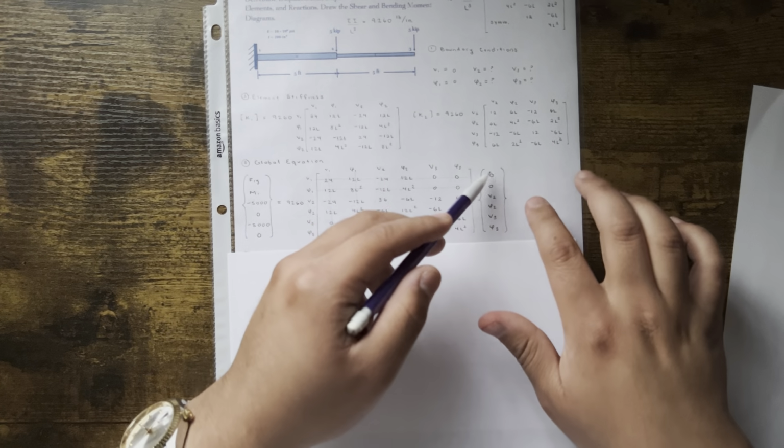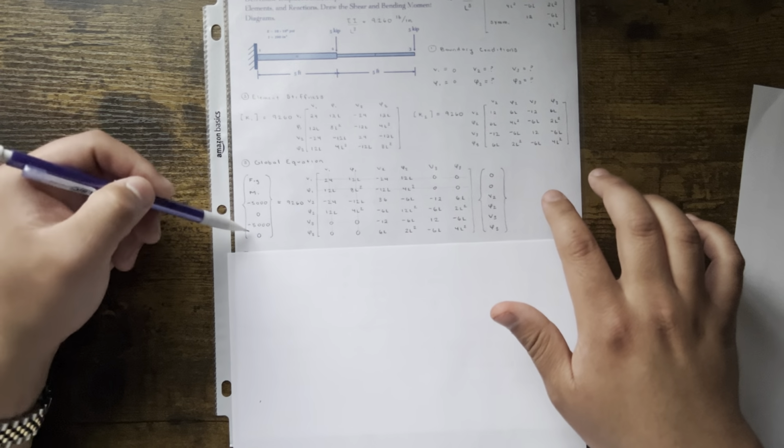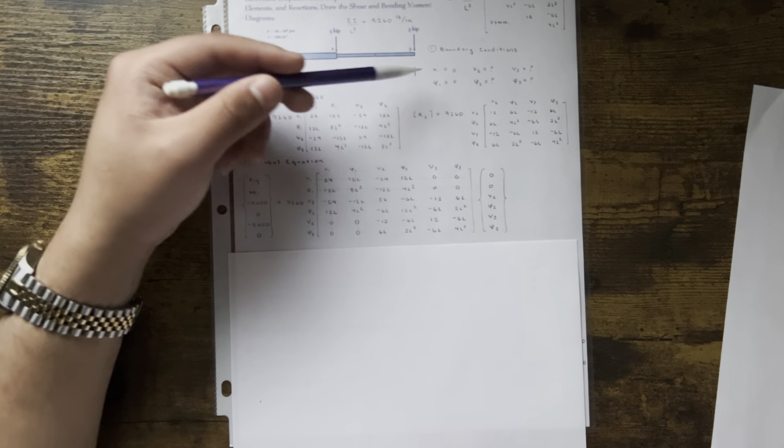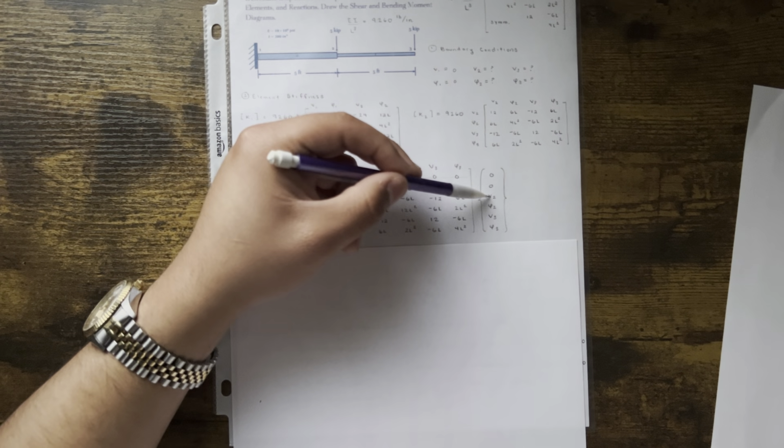So in this case, since we know the displacement, we won't know the force. And if you know the force, you won't know the displacement. So before you got to this, it's good to see this. Know your boundary conditions, right? We had 2 of them out of 6, 0 and 0. So that means we don't know F1y and M1. Because we didn't know these 4, we should know these right here, okay?